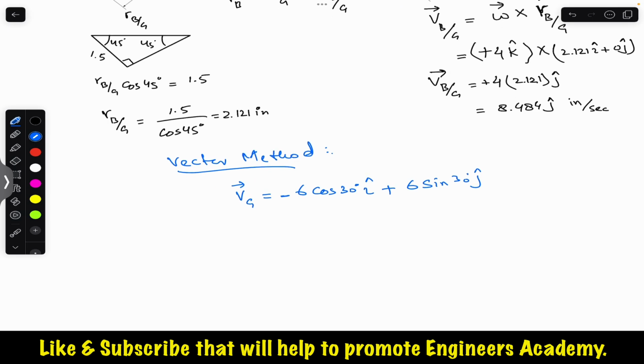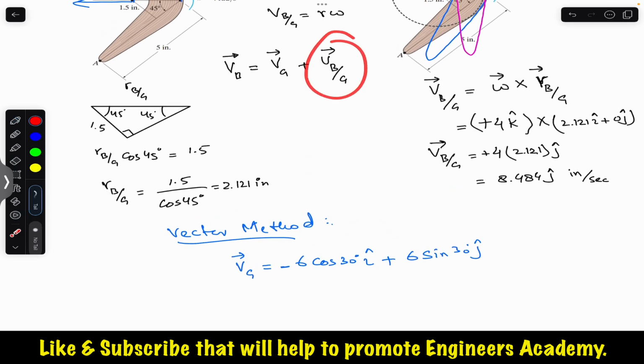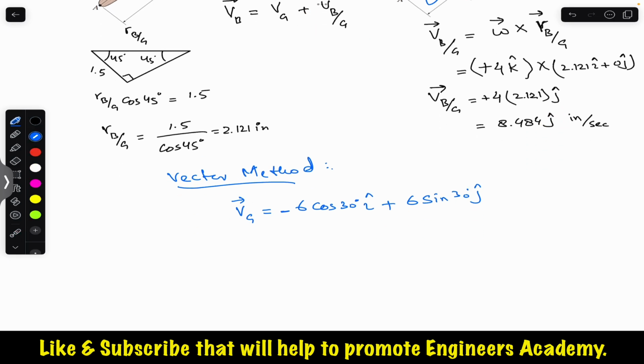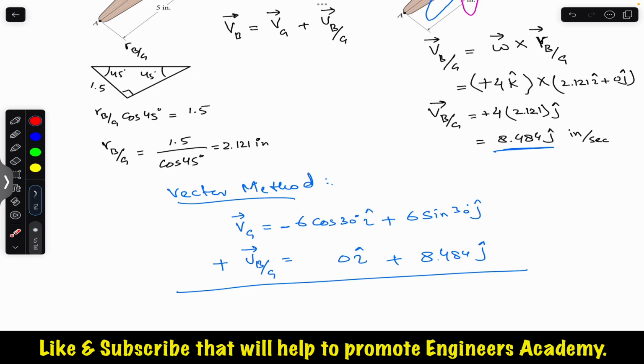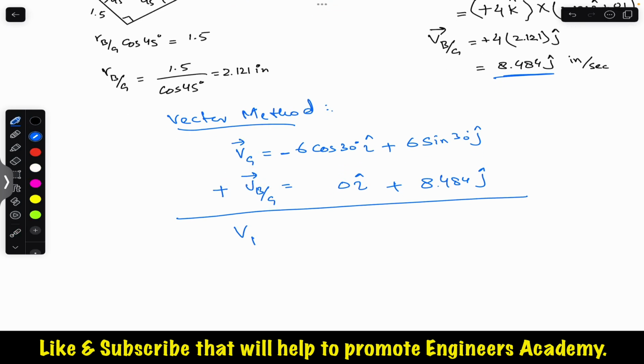And similarly, now we know that the velocity of B relative to G is 8.484, and it is in the positive J. So we can write that this is 0I plus 8.484 J. So for the vector method, we need to add up both of these. From this equation, we can see that VG plus the velocity of B relative to G, the sum of both of these will give us VB.